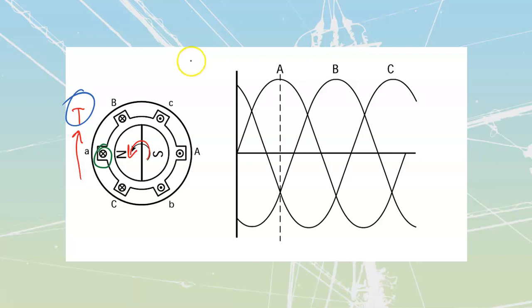Going back to dot and cross, if it's been a while since you've gone through that, dot and cross is basically looking at either end of a conductor, and you can look at them as if there was an actual arrow traveling through them. We'll stick some feathers on that end, we'll stick an arrowhead on this end. If the arrow's coming towards you, you're going to see the point, a dot. If the arrow is traveling away from you, you are going to see an X, or the fletches traveling away from you. And so we see that inside of here because we just used that left-hand rule.